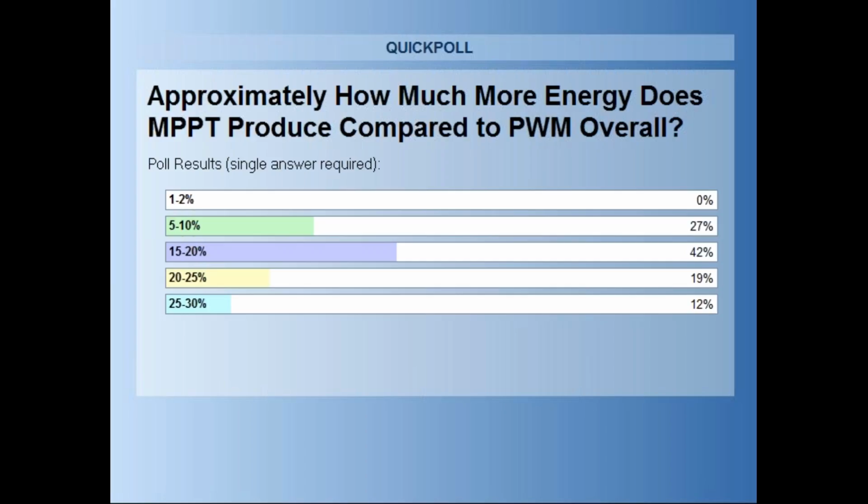It may not be worth that extra 8% for the extra cost of the maximum power point tracker. It might be cheaper to add another module. Since the cost of solar has come down dramatically over the years, the need for a maximum power point tracker just to get a little extra out of the solar array seems to not really justify the additional cost.